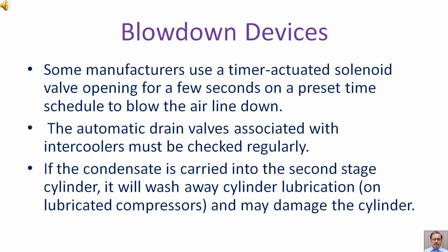Some manufacturers use a timer actuated solenoid valve opening for a few seconds on a preset time schedule to blow the air line down. The automatic drain valves associated with intercoolers must be checked regularly. If the condensate is carried into the second stage cylinder, it will wash away cylinder lubrication on lubricated compressors and may damage the cylinder.